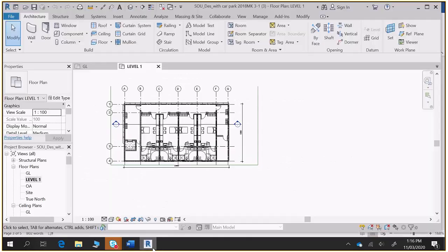On the Revit model, what I did want to show is we can treat all these walls through the centre as non-load bearing walls. I'd treat this wall along here as a load bearing wall, and this wall along the front as a load bearing wall as well.